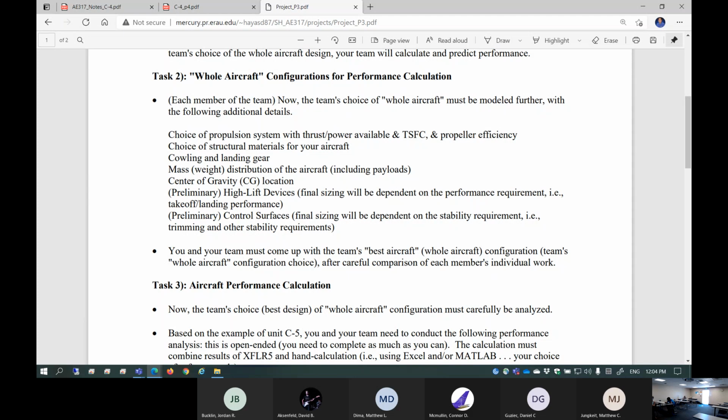And then if the neutral point is forward of center of gravity, that's a big issue. Your airplane is unstable. So you have to do something. You have to shift your neutral point by increasing the volume of tail or some other things. Okay, configuration change might be required for the phase 4. Now, at this moment, don't worry too much about that. Stability is not going to be discussed in phase 3. Okay, so phase 4, because of the needs of making your airplane stable, you may change some configuration, but it's probably not going to happen in phase 3.